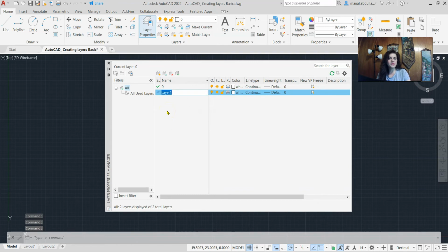this is layer 1. Several students leave it as layer 1 and go ahead. Also, I don't recommend this. Please give it a name. You need to organize the drawing, so you need to see what you're drawing about. If it's a house plan, you need layers for walls, windows, doors, dimensions, text, furniture, and bathroom fixtures. Think about what layers you need.